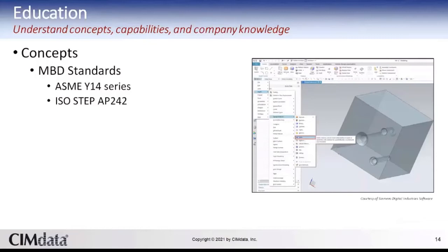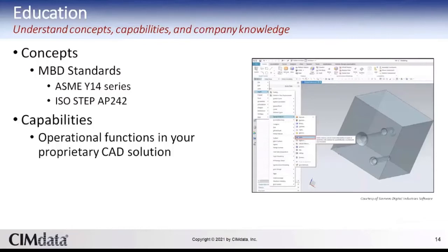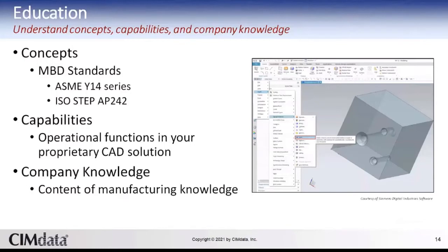First step is to put together a transition team and educate yourself. You should really focus on 3 areas. Number 1, model-based definition and PMI concepts. The standards are presented in the ASME Y14 series of standards and ISO STEP AP 242. Number 2, learn in detail what your CAD solution provider supports for PMI and MBD.